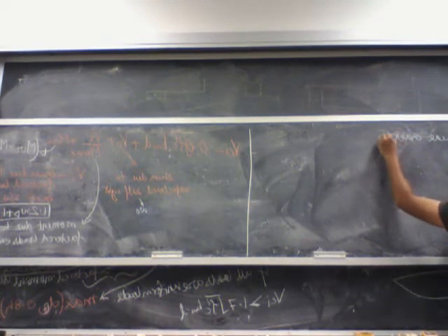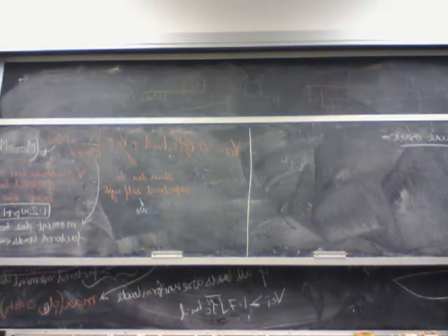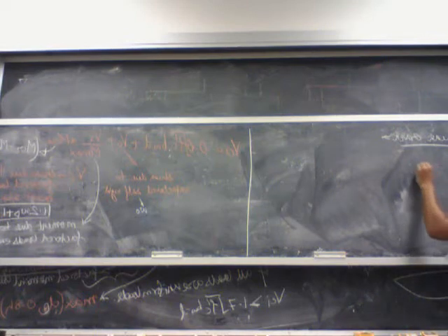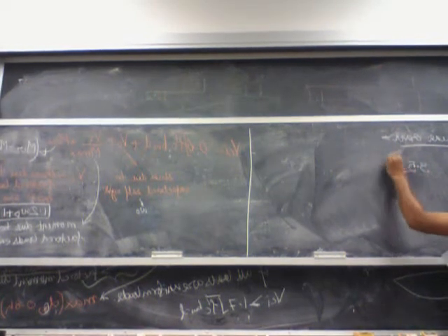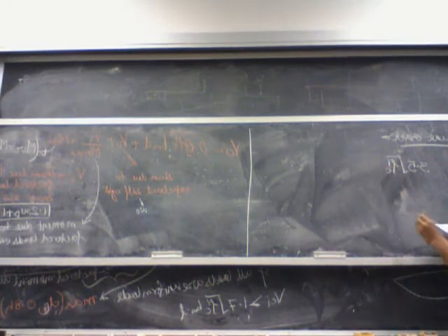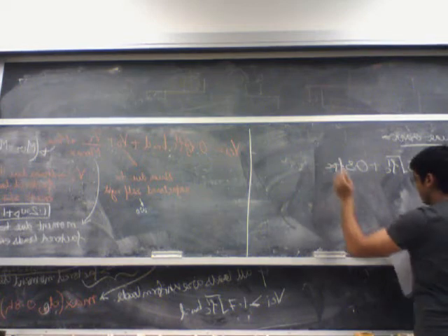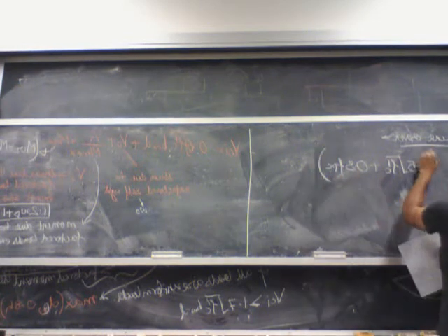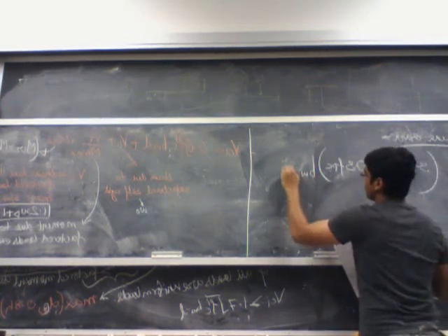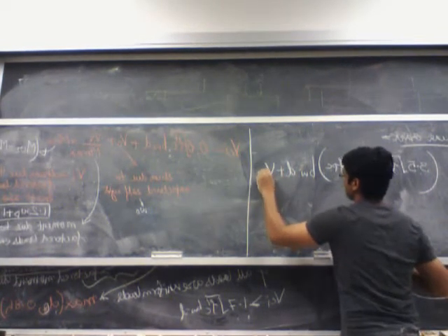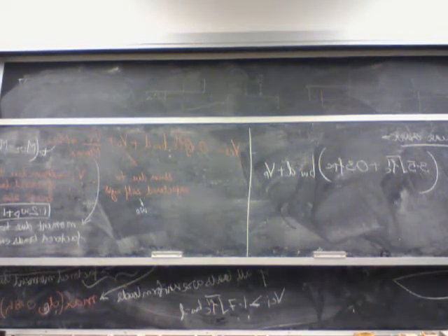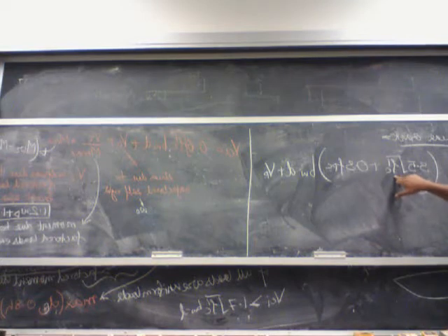web shear crack, you have a formula VCW, and this is (3.5 square root f prime c plus 0.3 fpc) bw d plus Vp. Again, rule of thumb: as soon as you see a square root of f prime c, it's always in psi. Okay, so this is in psi.